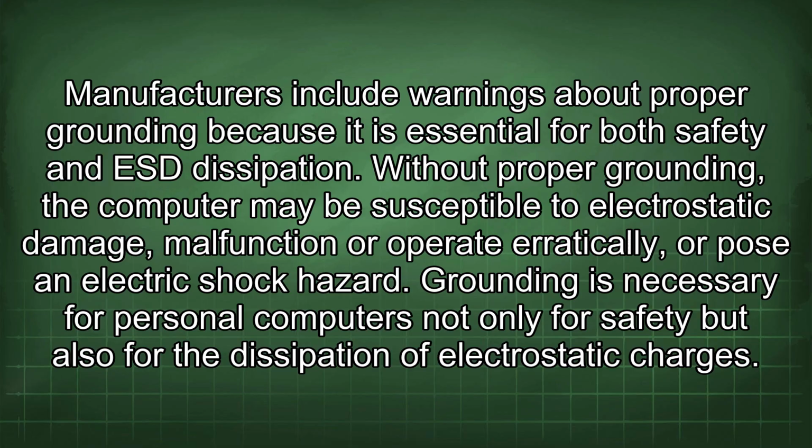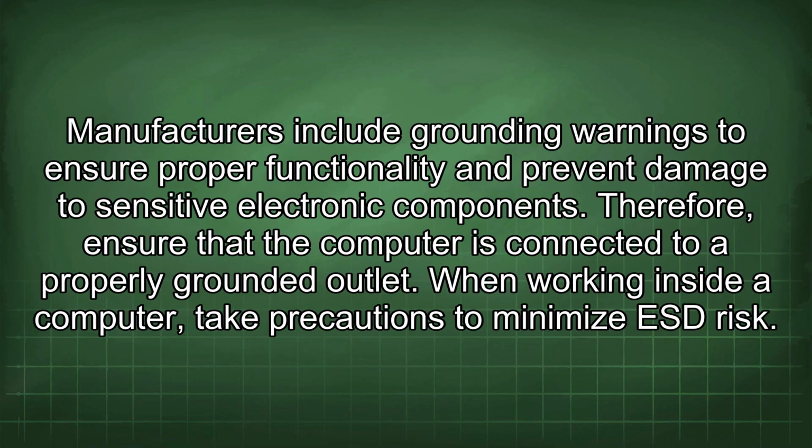Without proper grounding, the computer may be susceptible to electrostatic damage, malfunction, operate erratically, or pose an electric shock hazard. Grounding is necessary for personal computers not only for safety but also for the dissipation of electrostatic charges. Manufacturers include grounding warnings to ensure proper functionality and prevent damage to sensitive electronic components. Therefore, ensure that the computer is connected to a properly grounded outlet.